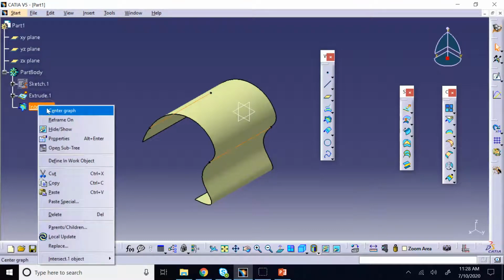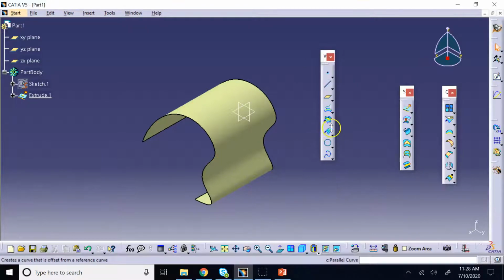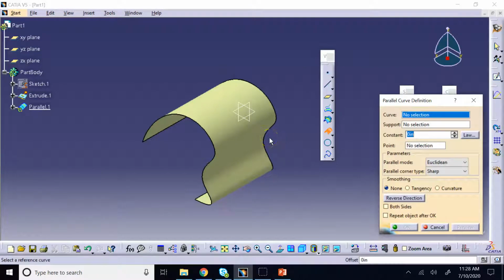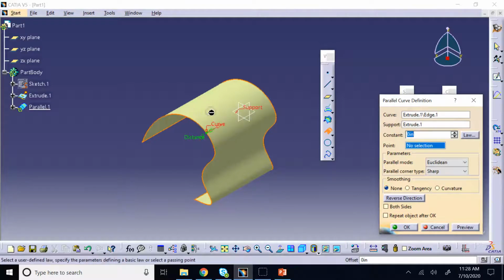But instead of one plane with one surface, you can have several planes with one surface and get parallel curves basically. So say I want parallel curves, okay, and then it says on which support, say on this guy, and then here you provide some gap, and you see now I could create a curve parallel to that with the surface, or actually it's like cutting the surface with a plane that is 1 inch from the front side, right?